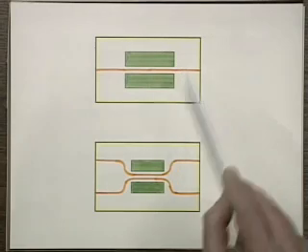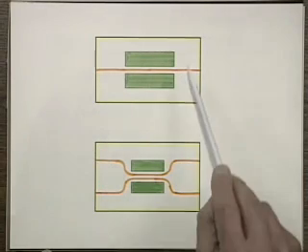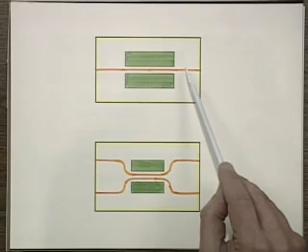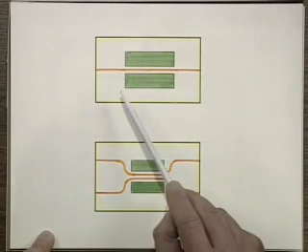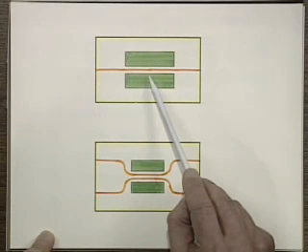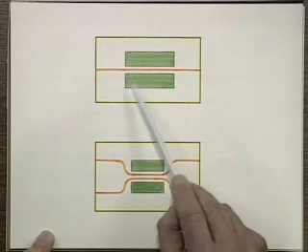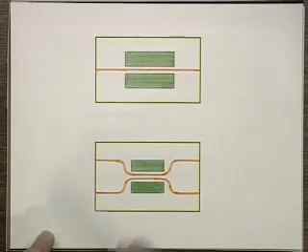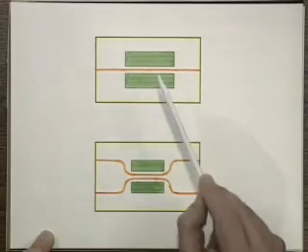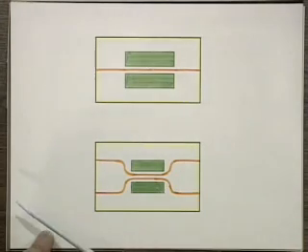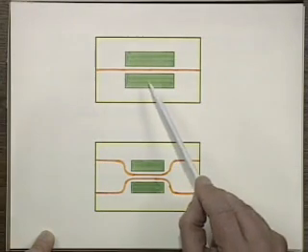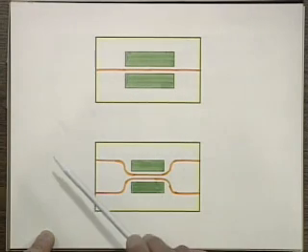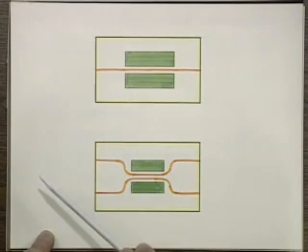All right. So now, how do you create a phase modulator here? If this material is, for example, slightly electro-optic, then by putting electrodes here and applying a voltage difference between them, you can change the index, either in the cladding or in the core, simply by applying a voltage. This way, you can phase modulate the light propagating in this section. You can do it pretty fast, and then you can get very fast phase modulators. And if you ramp the phase using serrodyne techniques, you can also do frequency shifting quite easily using this device.